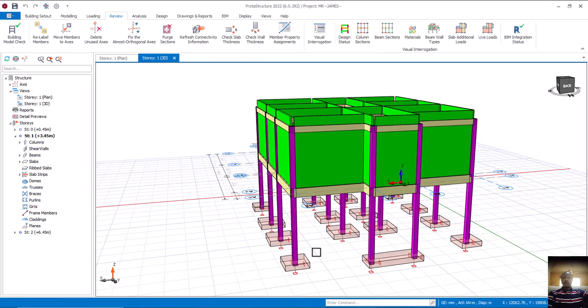Why do we hinge our beam? Is that okay? So number one is to represent actual structural behavior. Some connections in real structures are designed to carry only axial forces and shear, not moment. Do you get it now? So some of your members are meant to carry axial forces and shear, not moment. So in such a scenario, or in that particular place, hinging is very key. Is that okay? Like all this pin connection in trusses and some steel connections.